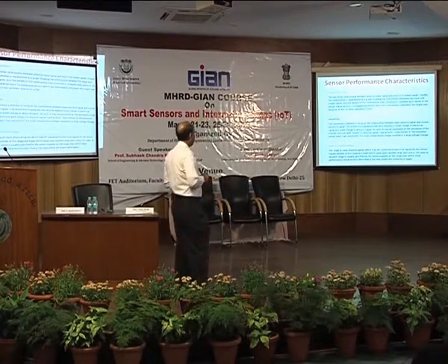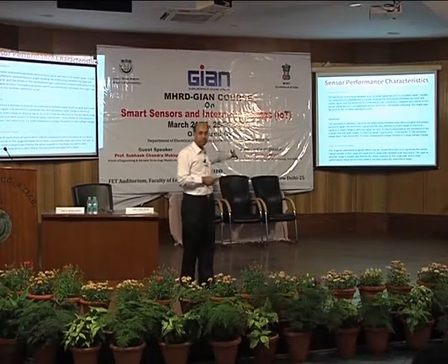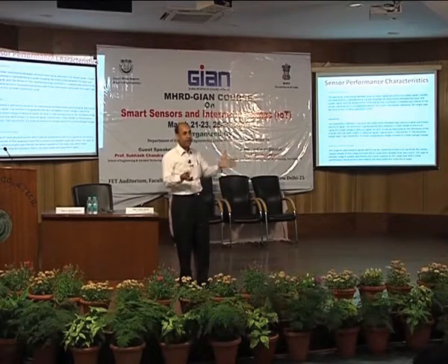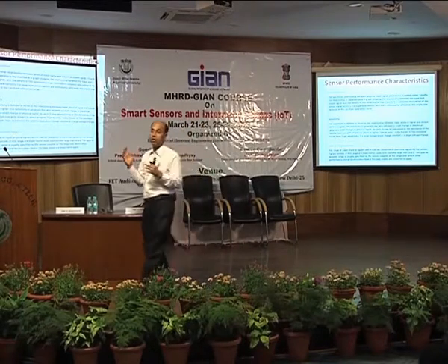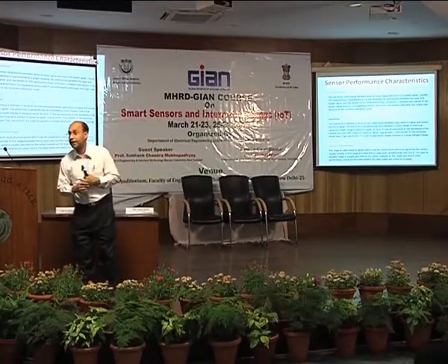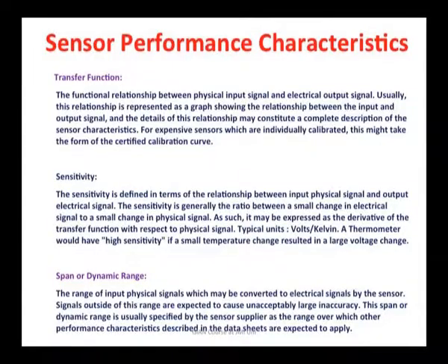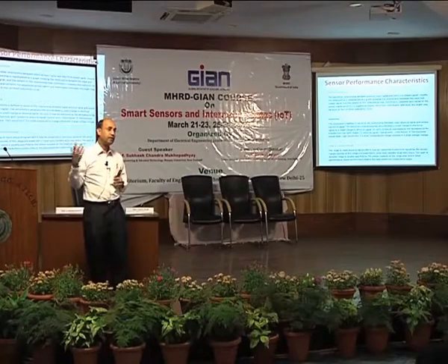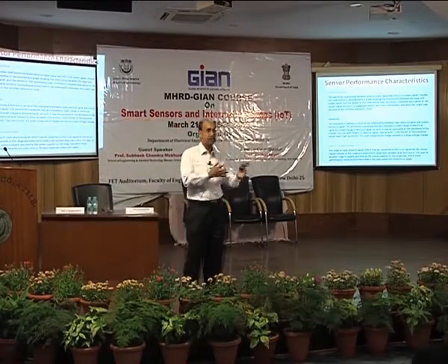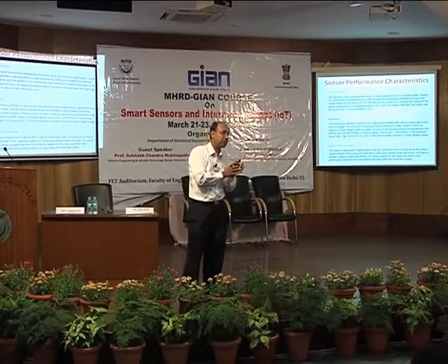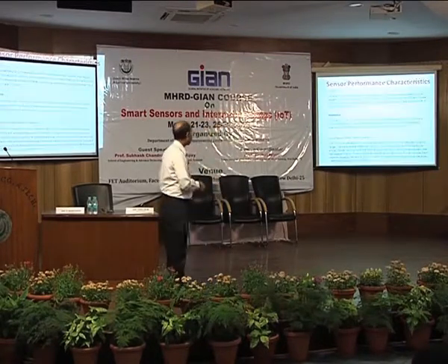So you will be able to get all the terms of the sensor if you have the opportunity of doing the characterization. You can change one at a time from low value to high value, keep that constant, change the other, see the output, and then you can get a set of curves. You can define each and every one, and also you can define the cross sensitivity. Okay.